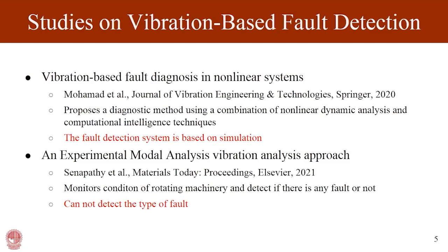Now, there have been several studies and researches done for machine fault detection. Firstly, we can talk about the vibration-based fault detection systems. The problem of these kinds of approaches is that these systems mostly are based on simulation data, not real industrial data sets. And those that use real industrial data sets can only tell if the machine is faulty. You cannot really specify the type of fault that is found in the machine. So it makes it really difficult to remedy the problem and find the source of the problem in the machine.